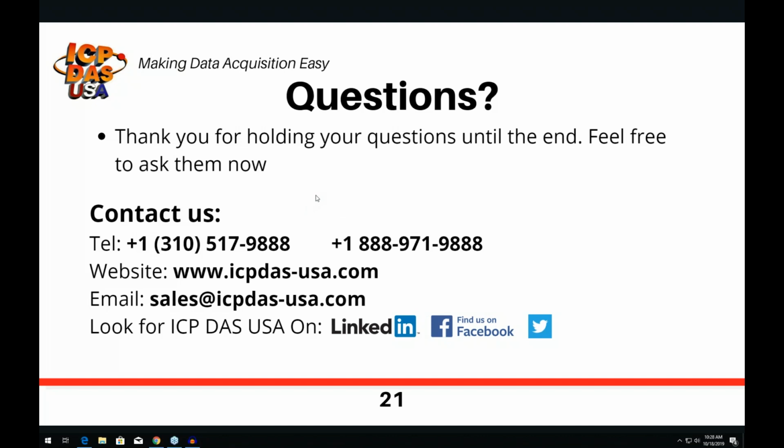The next question: is there a way to determine the best bit rate and baud rate to use given the RS-485 Modbus communication? Typically, the faster you communicate, the shorter the overall distance. If it's a very short bus, I recommend 115200, but 9600 is typically used for most standard applications. The farther you're transmitting, though, the slower the baud rate limitation. If you do want to get as fast a communication as possible, of course, faster baud rates are better. So probably start with the faster baud rates, maybe 19.2k or 115200, and if that doesn't work, then you can go down to like 9600 or even lower than that if necessary.